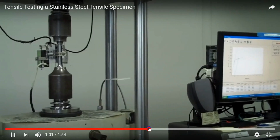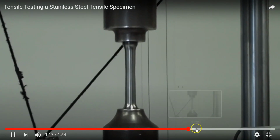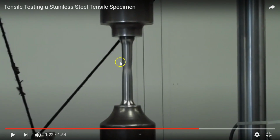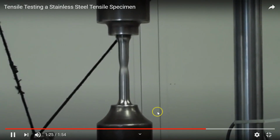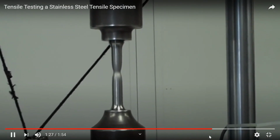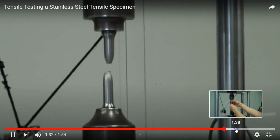Okay, so you see here is the part where the force is so high that this section of the part goes narrower, right? You see the cross section of the part is narrower here. This thing we call necking. And ultimately at that point, that's where the part starts to break at a 45-degree angle. So it's getting smaller and smaller, stress goes higher and higher, and there we go. We have failure.